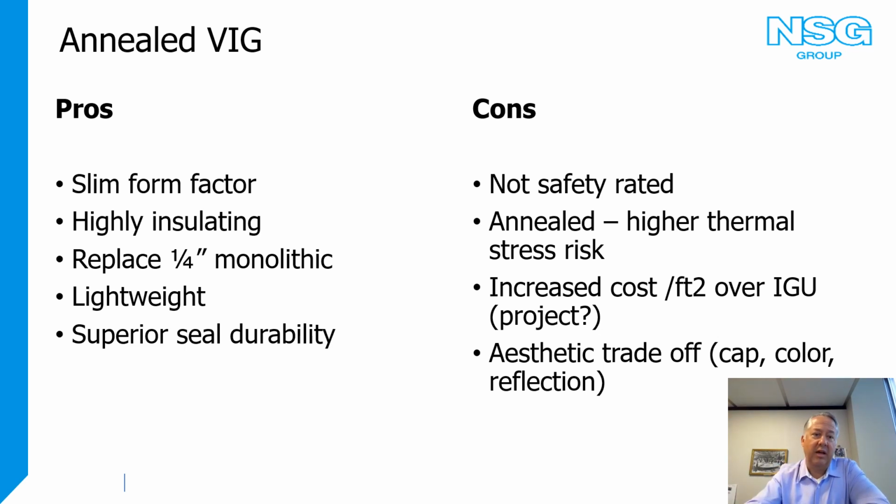It's a simple change out for monolithic glazing. It's lightweight, so it fits in the same spot. And then it's got a superior seal durability because it gets rid of the organic material on the edge. No more polyisobutylene or any of these seal materials. You have an inorganic glass or metal weld.